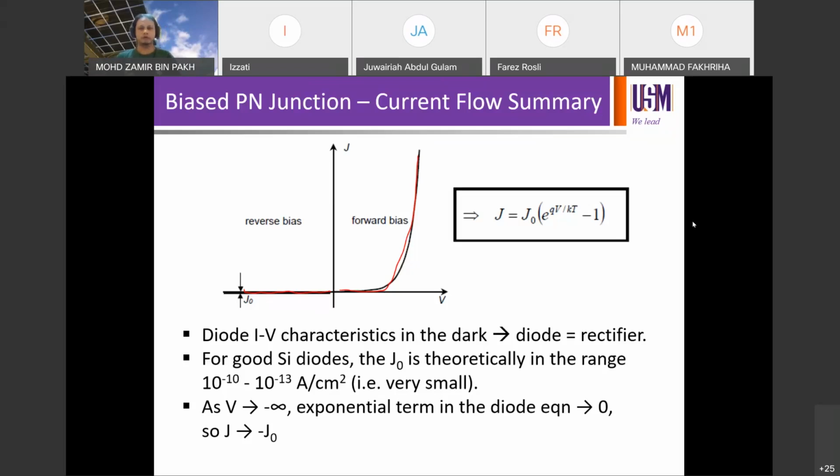So we have also learned that if your forward bias voltage is high enough, exceeding the turn-on voltage for the diode, or the knee voltage, which typically is about 0.6 to 0.7, then the diode will be on. So if you are supplying a forward bias voltage of less than 0.7, for example, to the junction, the diode will not be turned on because the energy supplied is not enough to overcome the barrier.